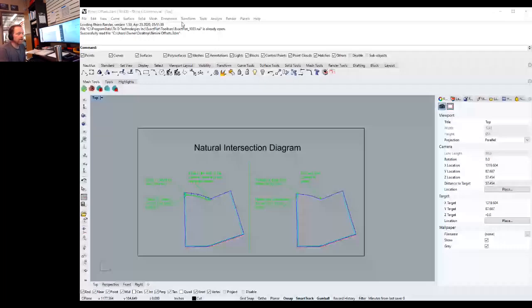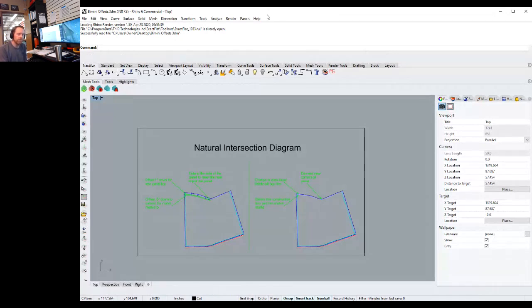Great question. An important one. So when you're patterning, you can see what's happening with the frames. When we would pattern traditionally, we would preload the frames front to back, and we would take our template. We do it exactly the same way with the ProLiner. But there's another variable. When we were patterning by hand, there's only a few people, I know Kyle is one of them, that'll actually pattern an entire boat, right? But when we would pattern by hand, we would do the bimini first, and then we pattern the enclosure, right? So when we pattern the enclosure, there's a little bit of a downward pull.